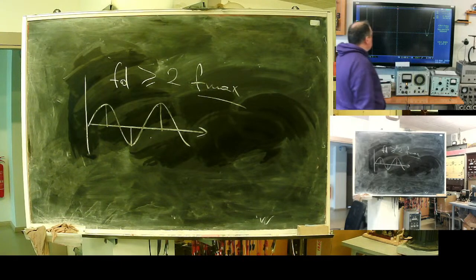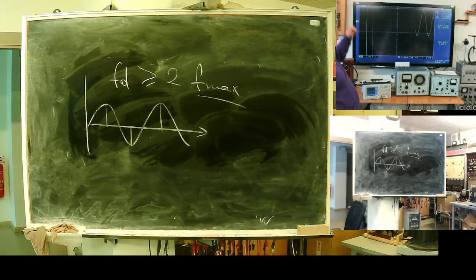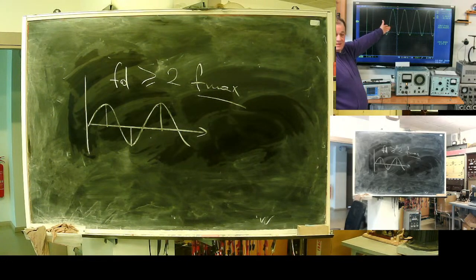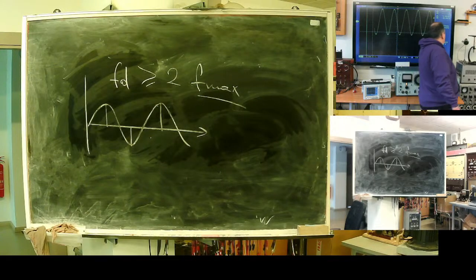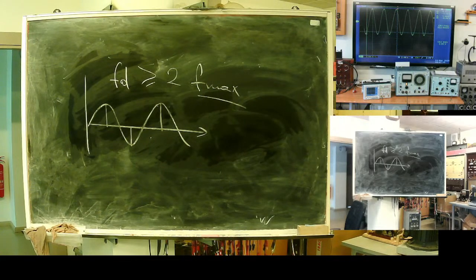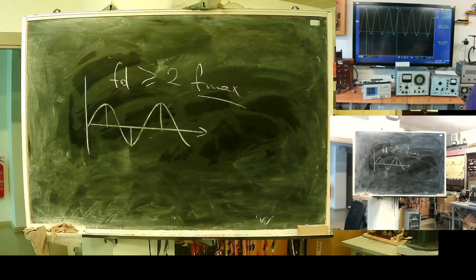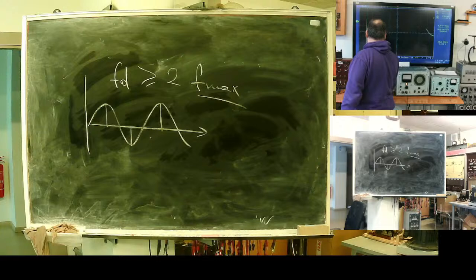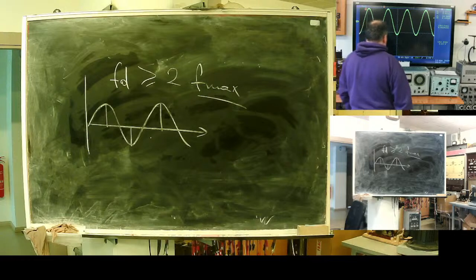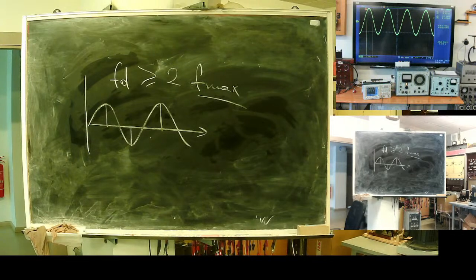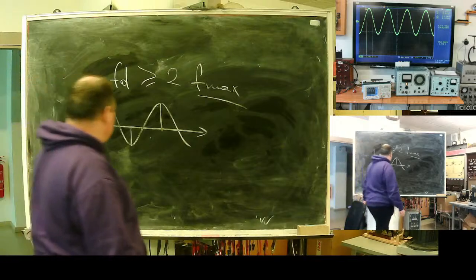Oh, you will like this. Nice sine, except one tiny movement, frequency of 300 millihertz, while its actual frequency is 10 kilohertz. It's a clear example of aliasing. Here it is real, 10 kilohertz. I can attach an analog scope and you'll see.